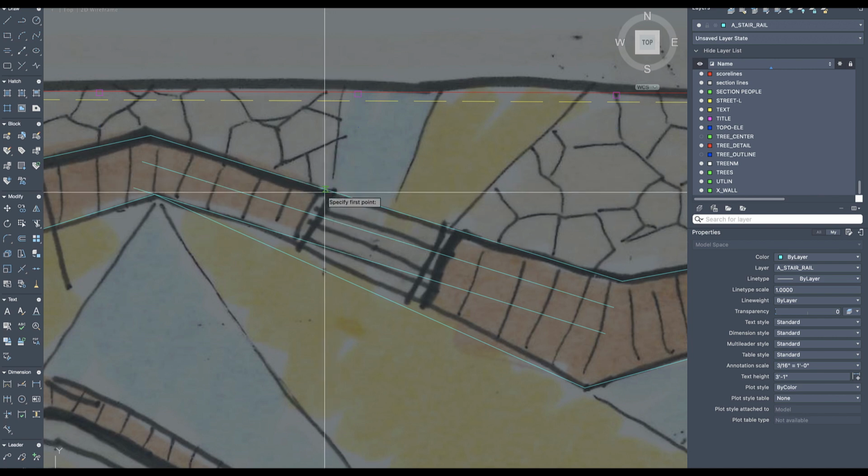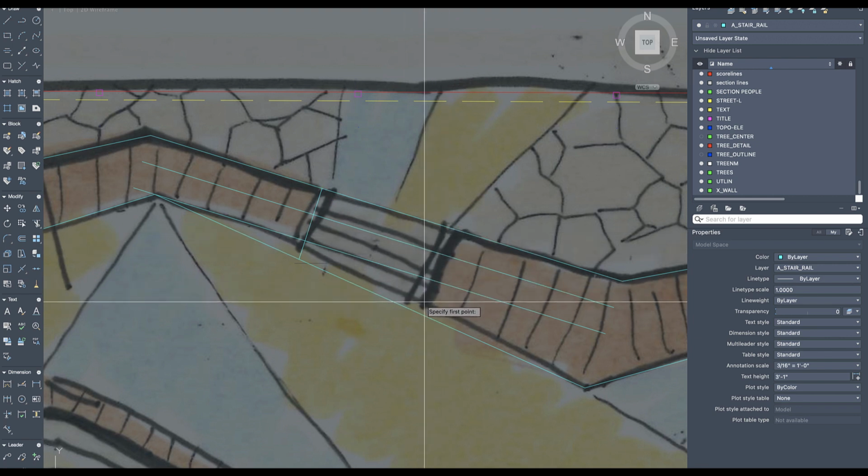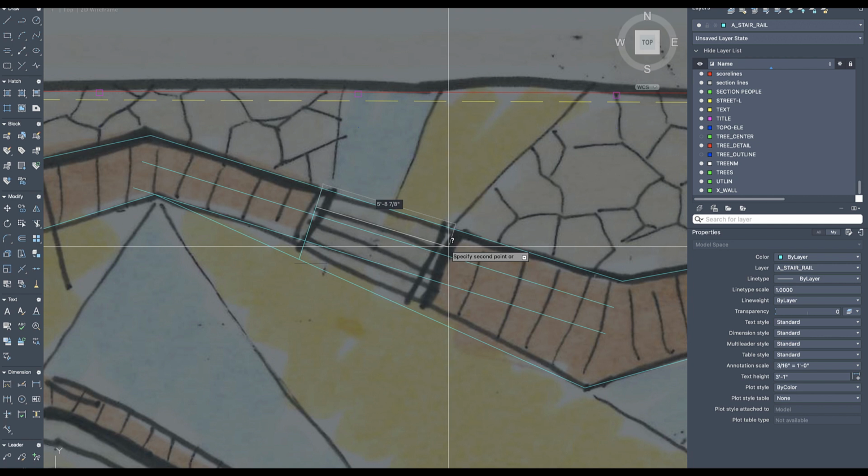At this point, we're going to create a few lines where maybe we start here and then we snap to perpendicular. We can do the same here and snap to perpendicular. I want to test out just a distance here, and we'll probably just get a whole number. So we have it drawn about 5 feet 8 inches. I'm probably going to just offset that 6 feet. Nice round number. If it's a little far, we could grab both of these lines and move them back, find that right spot for it. But it gives us a whole number for the depth of those stairs right there.